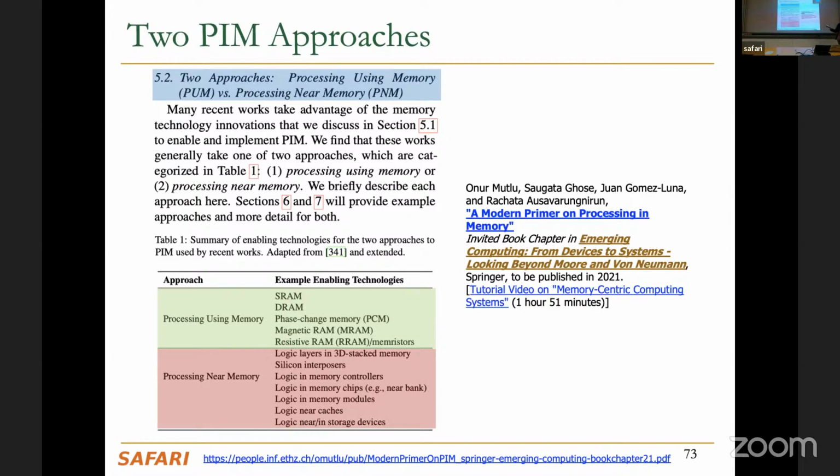But if you have a sensor, probably this sensor will have to send data to some central processing unit, a CPU, for example, and before sending the data it will have to store it somewhere, right? Maybe an SRAM or maybe a small DRAM. So you could have processing in memory near the sensor as well, or inside the sensor as well.